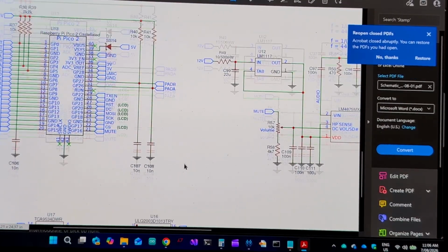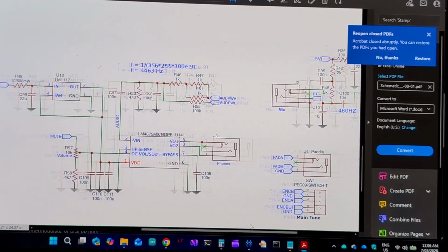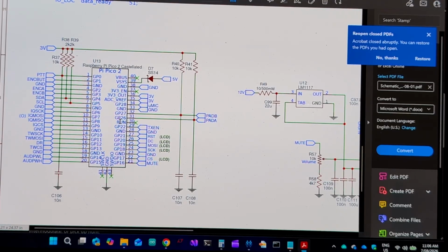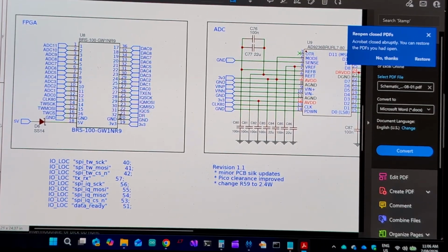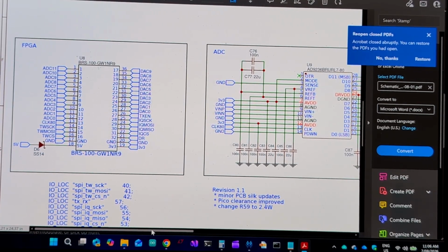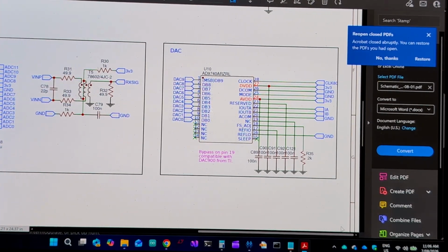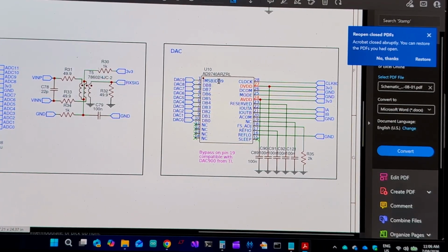The transmit path obviously starts with the microphone here. The microcontroller generates IQ transmit at baseband, sends that to the FPGA, which does the up conversion to the frequency you want to transmit on. And that is output on the 10 pins for the DAC, digital analog converter, here, clocked at 80 megahertz. This is directly from the data sheet, the AD9740.